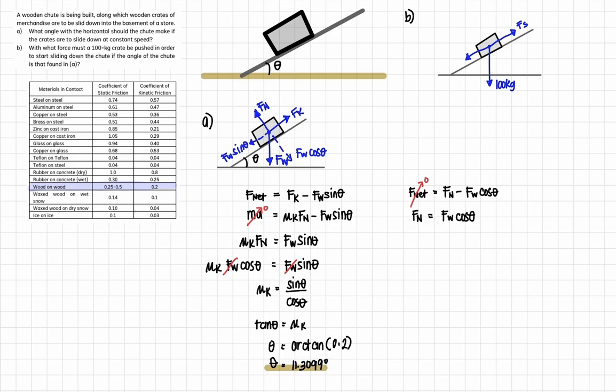So if this is the weight downward, let's make that Fw. So we have Fw sine of theta. This is our angle theta here. But there is another force that is applied, the applied force to be overcome. And then we have the force perpendicular to the plane, which is Fw cosine theta.